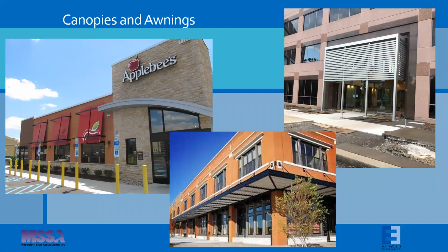It may only be 2 or 3 inches, but if you can envision an EIFS surface on a wall, the EIFS provides no structural support to that bolt. So it's sticking out 3 inches and is cantilevered by the weight of the canopy. That unsupported gap can be significant. It's a little bit esoteric, but again, the engineer needs to take that into account to make sure those bolts are sized properly.